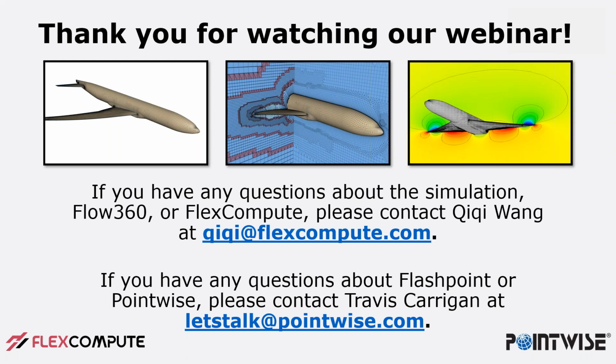And in fact, if you run the Flashpoint surface meshing, you get a surface mesh, you grab that domain and go into the domain solver, and you can see everything that Flashpoint has done. You can see all of the boundary conditions that it's set up for 2D T-Rex, all of the attributes and everything like that. If you look at the boundary conditions for 2D T-Rex, you'll notice that at the leading edge, an area of high curvature, it uses the angle BC. It sets that angle to the value that was in the global tab. So that's how you would control that initial height.